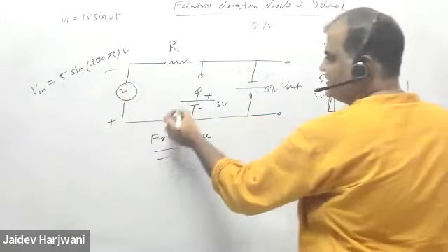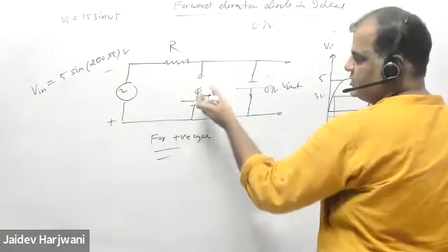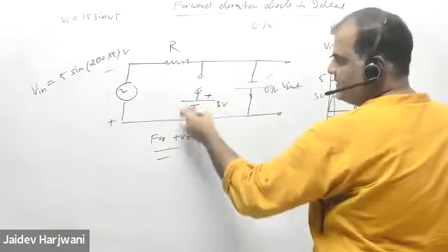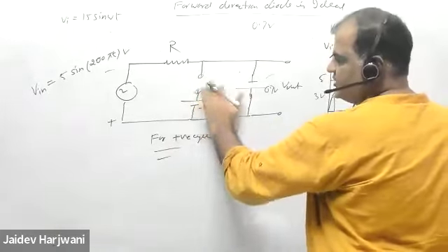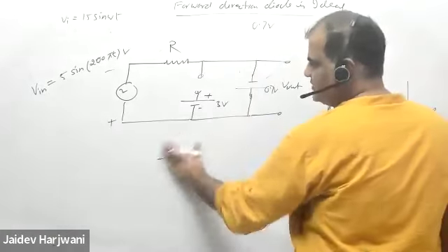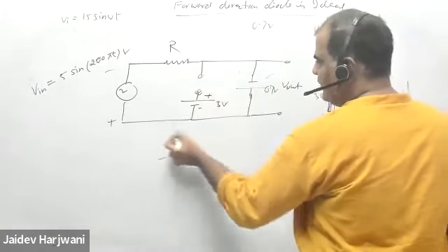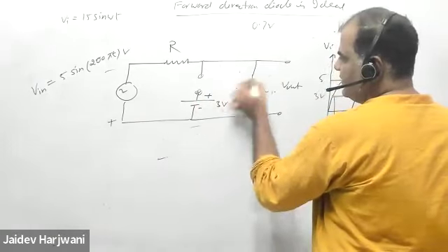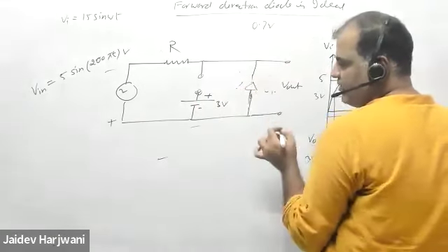Current is coming like this. This is already reverse bias. Now you're putting plus and minus more, this is already reverse bias. So this branch is open, no issue. This branch cannot conduct. Only now this diode becomes forward bias. The Zener diode becomes forward bias.